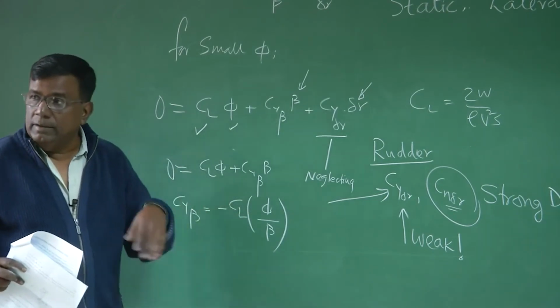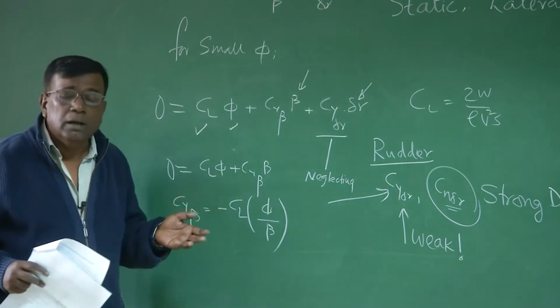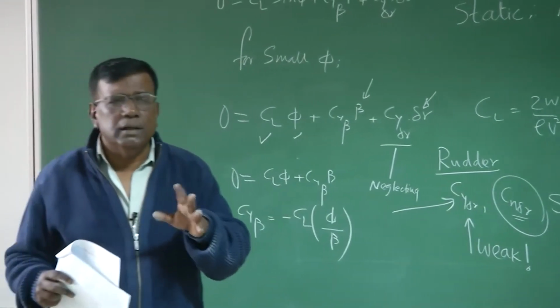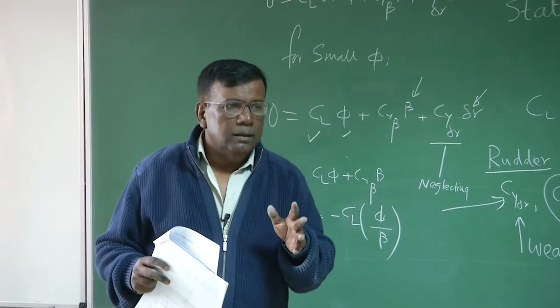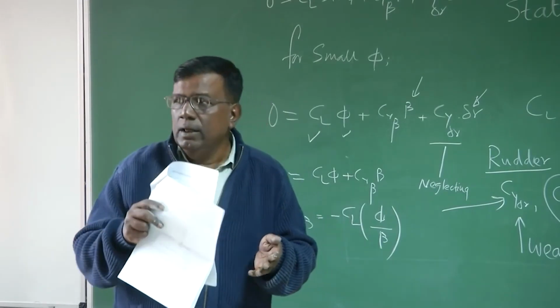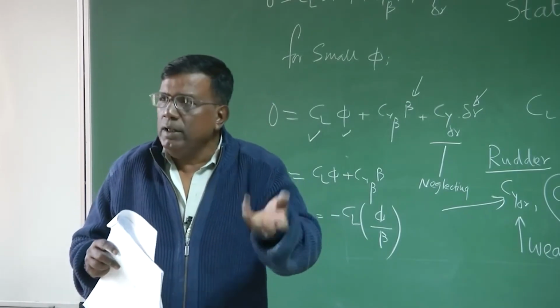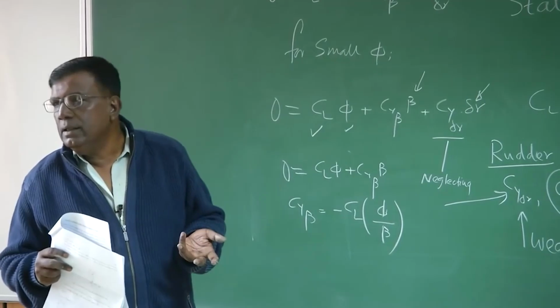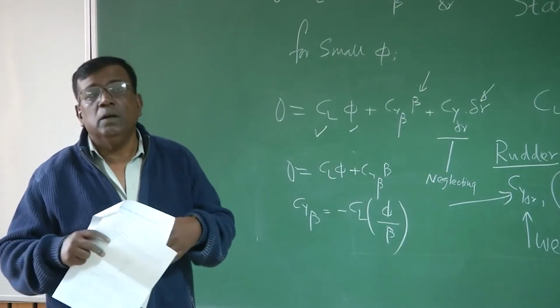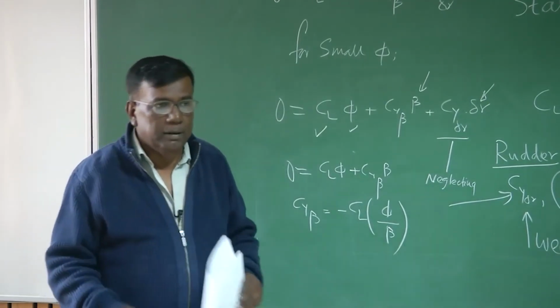You are getting that estimate. These tests are very important when you do some minor modification in the vertical tail. Suppose some minor changes there, right? You only do steady side slip maneuver, you get how much Cy beta has changed, for marginal changes. Otherwise, you go for thorough flight test experiments, which are rigorous.